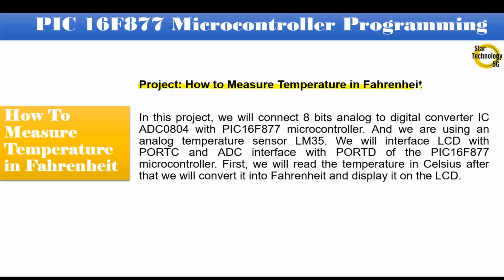Project: How to measure temperature in Fahrenheit. In this project, we will connect 8 bits analog to digital converter IC ADC0804 with PIC16F877 microcontroller. And we are using an analog temperature sensor LM35. We will interface LCD with port C and ADC interface with port D of the PIC16F877 microcontroller. First, we will read the temperature in Celsius. After that we will convert it into Fahrenheit and display it on the LCD.